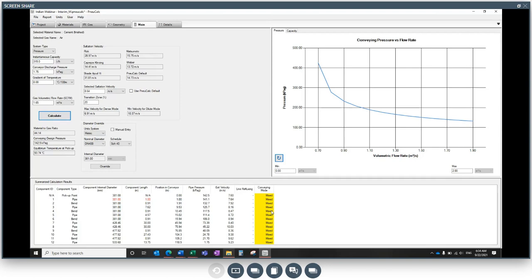The reason is that we didn't change our volumetric flow rate and we didn't play with our piping so far. So we're going to do that in just a moment. But by using the blow tanks, we're going to be able to work at a higher pressure, right? And we're going to be able to use a lower flow rate. And in turn, this is going to allow us to use a smaller pipe diameter and keep the same material